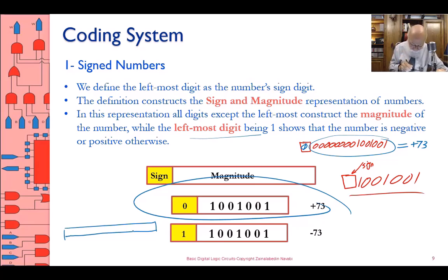And then in this fixed point, we are using, let's say, 8 bits for the fractional. What it means is that there is this binary point after the 8th bit. Okay, then we have 23 bits for the integer part, and then always 1 bit for the sign bit, and then that 1 bit is either 0 or 1 for positive or negative.